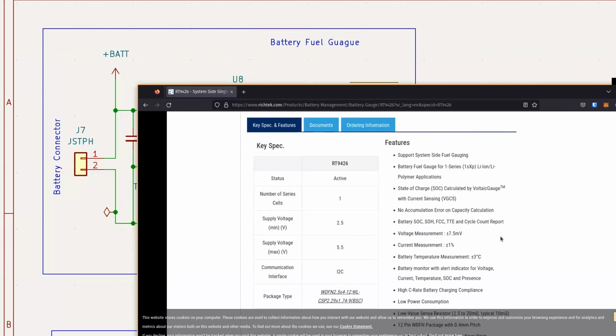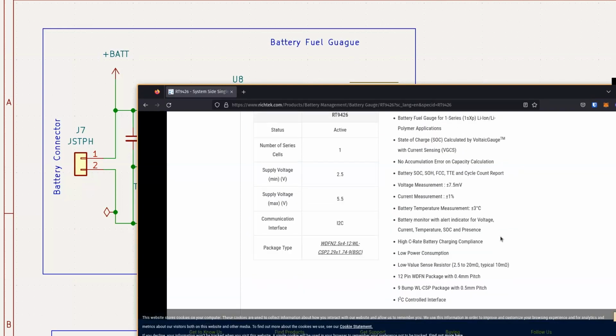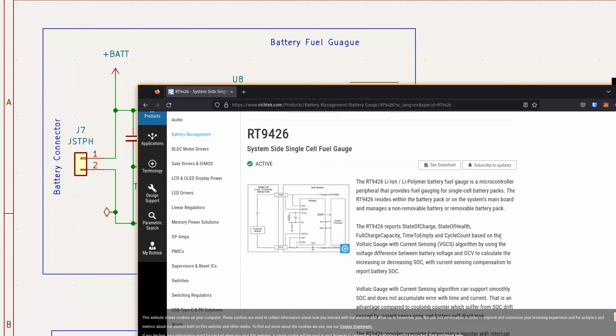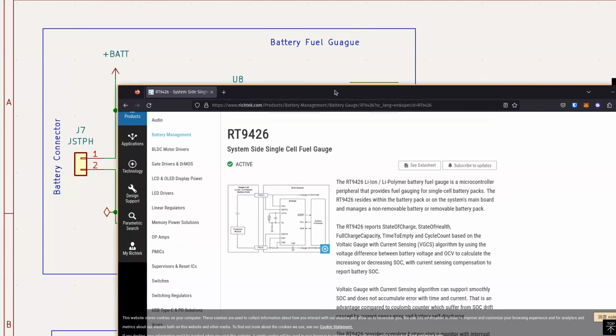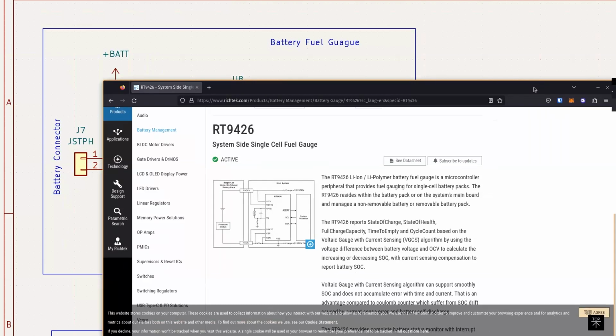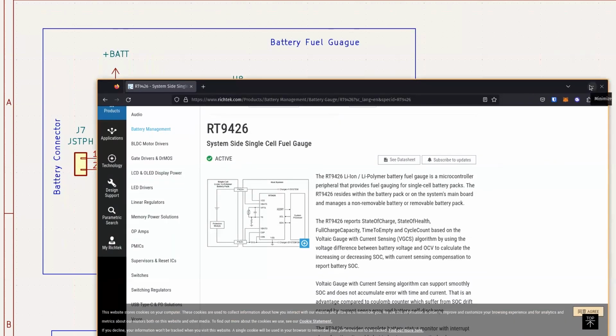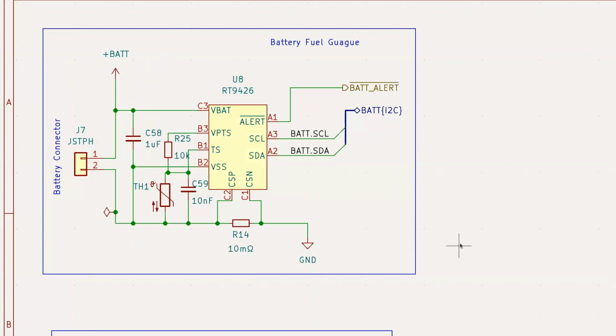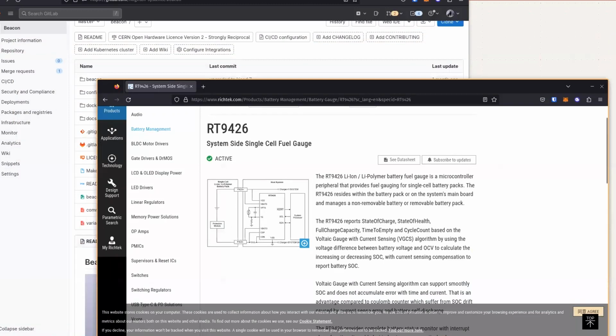Just looking at it from an electrical network standpoint, I see a little bit of benefit, but note that if you don't want to use this or don't see a need, it's just drawing more power and parasitics. If you could do it a simpler way, maybe that's something we need to consider. I think that's why these chips came into widespread use, because just using a voltage divider doesn't get you as accurate as you want to be. I know there's a TI chip, which is why I asked that question, and it's in pretty widespread use.